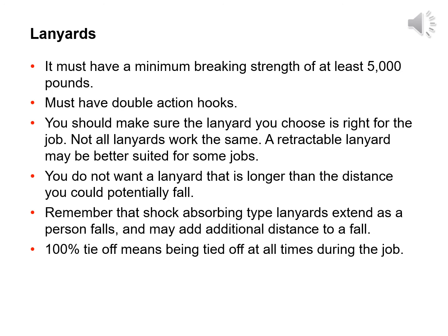100% tie-off means being tied off at all times during the job. On a dual-hook lanyard, at least one hook must be secured at all times, even when moving.